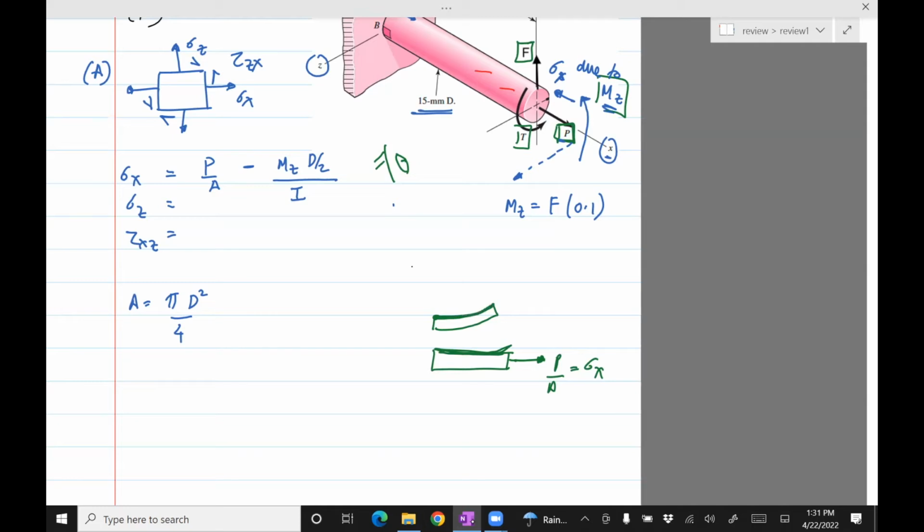If something is bending here, then the stress has to be acting in this fashion, in other words, from right to left. So the sigma x due to M would be like this. One of them is to the right, one of them is to the left, and that's why there's a negative sign. I just stuck with the convention that positive is along the positive x. So this is positive, and this one is in the opposite direction, so negative.